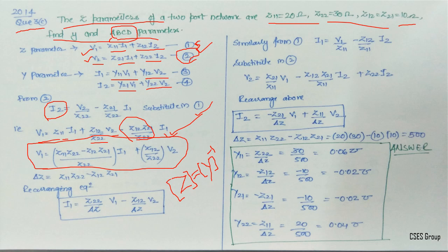So please remember this relationship, guys. Impedance is always the inverse of admittance. Hence you can always write Y as the inverse of Z in matrix form. Just write y11, y12, y21 and y22 in the standard matrix notation, and for Z also in the same way, and just do the inversion. You will get these equations.